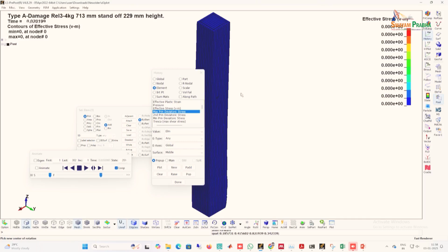Usually those are not of that great interest other than you want to show where the high stress regions are, or you kind of want to simulate cracked regions and show the high stress regions. You can adjust your effective stress ranges and then show peak. Otherwise, these are visually good. History plots are often more useful than others.